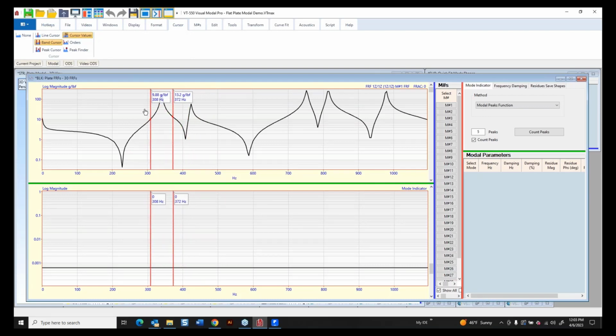Now just imagine that I got some data and I got a nice clean mode here at this frequency, but maybe I got a whole bunch of garbage out here, a bunch of high frequency stuff that showed up in my measurements, and it's very common. Just a whole bunch of high frequency noise or stuff that I just couldn't get out with my analyzer or my signal processing. But if I've got a nice clean peak here, and even if I got mass loading and the peak is moving around, I can do a quick fit here.